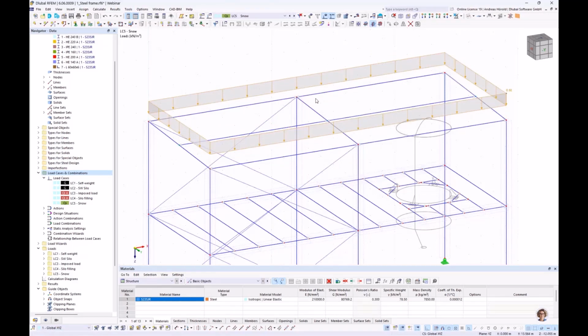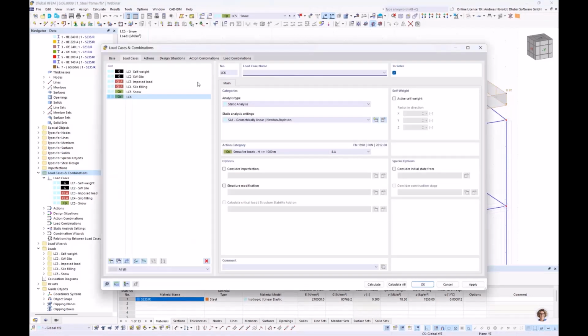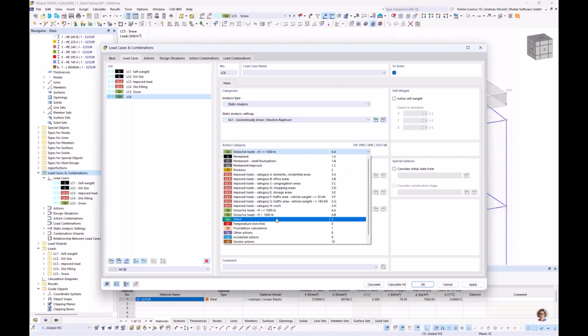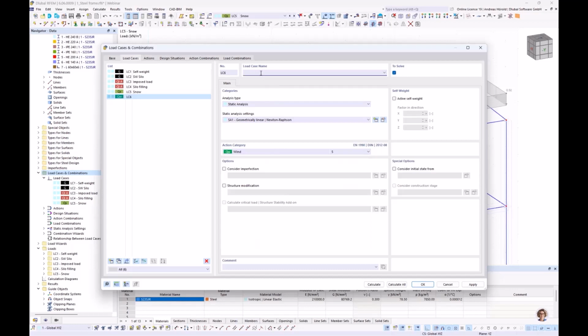So then we create the next load cases. I go to new load case. We would like to consider 4 wind load cases: the wind in plus X direction and the wind in plus Y direction, with wind pressure and wind suction. So at first I changed the action category to wind, and I call it wind in X and pressure,